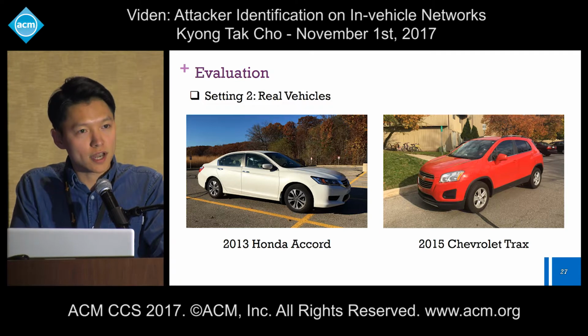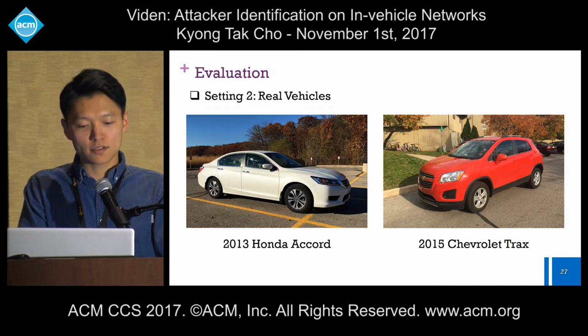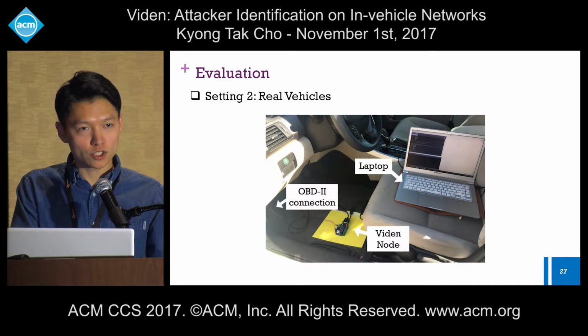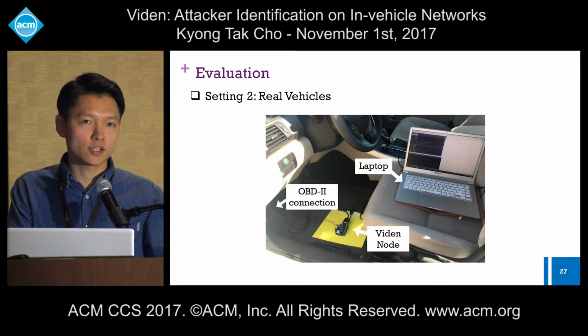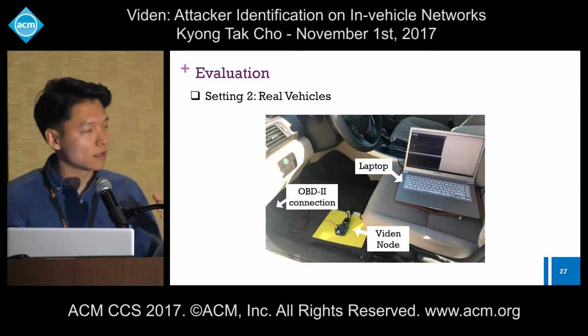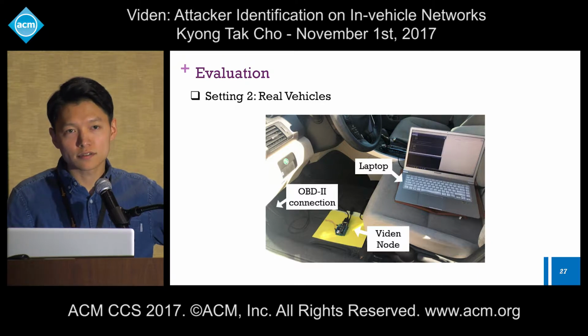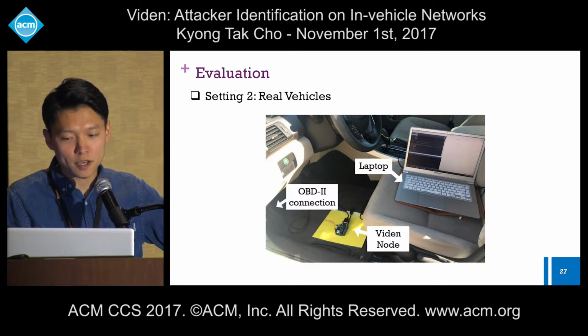To measure voltage outputs from those cars, we had to connect our Viden node to the OBD2 port, which provides that link to the CANH and CANL lines of the actual bus. And we also monitored and processed those measurements through our laptop.